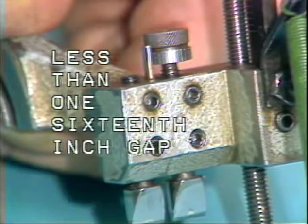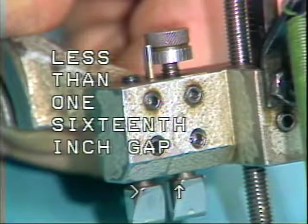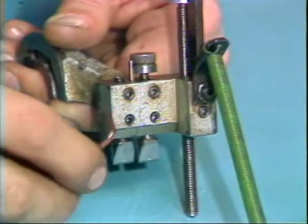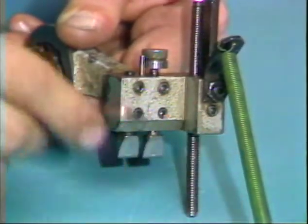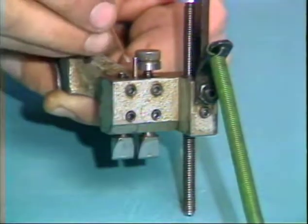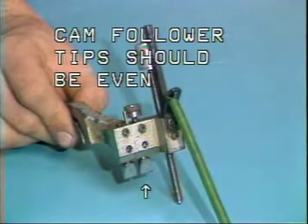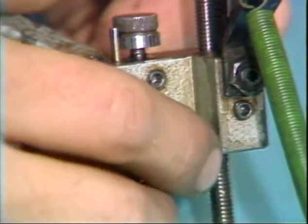After adjusting the cam follower, this gap between the cam follower and the attachment should be not more than 1/16 of an inch. Repeat the procedure for the other cam follower. Both cam follower tips should also be even. Tighten all the lock screws.